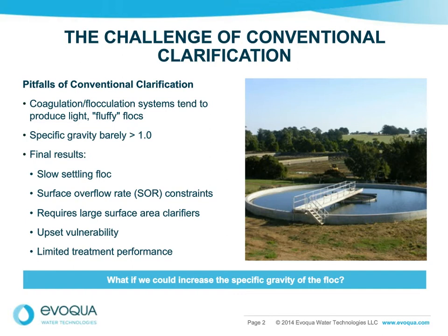To overcome those challenges, you typically either have to add larger surface area clarifiers or a downstream tertiary filtration step. But what if we could just add weight to those solids so they settle readily in a clarifier? That's what we'd like to talk to you about today: the ability to ballast clarification steps to get better settling, better effluent, and achieve a desired effluent quality.